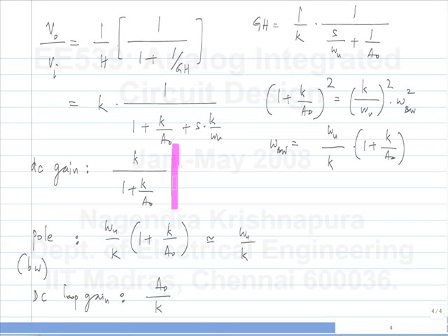In this case, the main effect is on the DC gain. The bandwidth is slightly affected, but we can ignore that for the most part. Okay. Now, the DC performance is important where you are concerned with where the value settles to, right? We are talking about DC performance or what the output settles to in the long term. Now, depending on the accuracy you want, you have to adjust the value of DC loop gain.